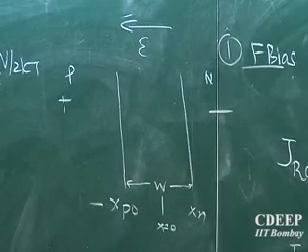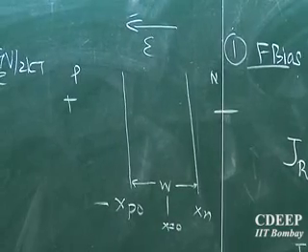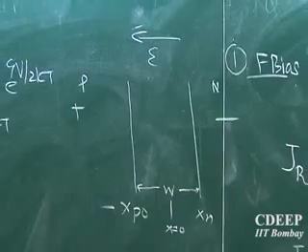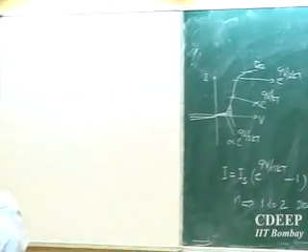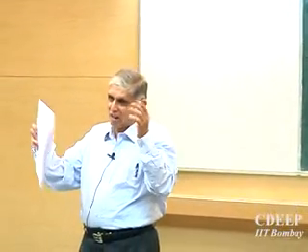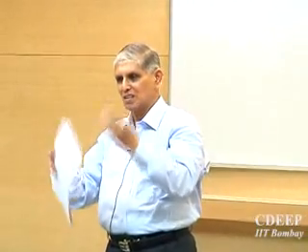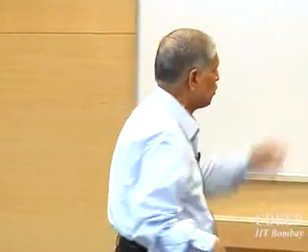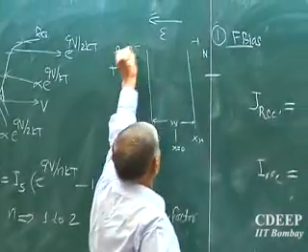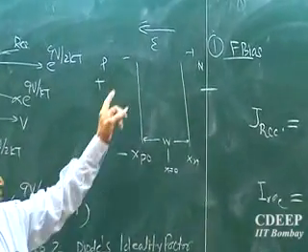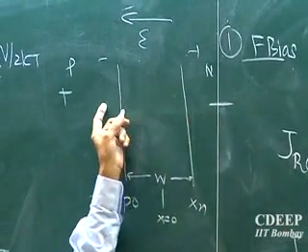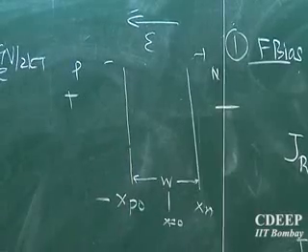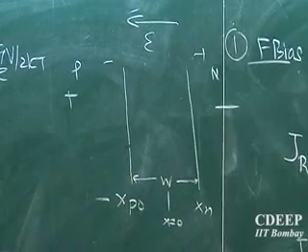However, one fact which I should have said: in any semiconductor, at any temperature, there is a constant generation-recombination. Is that clear? Everywhere the thermal term will always be present. The other carriers may exceed this value, but the generation-recombination term is always there. So you are pushing the carriers; which carriers are moving in reverse bias? Electrons from P will go to N, holes from N will go towards P, and they are not allowed to recombine.